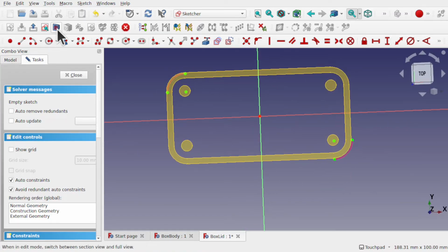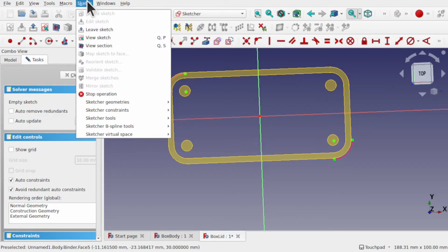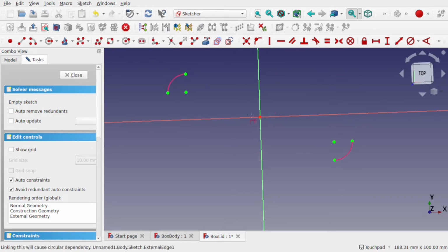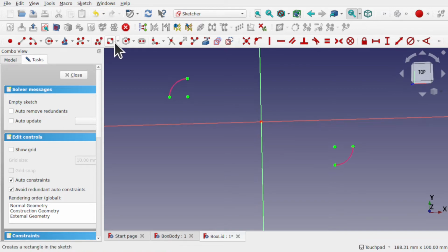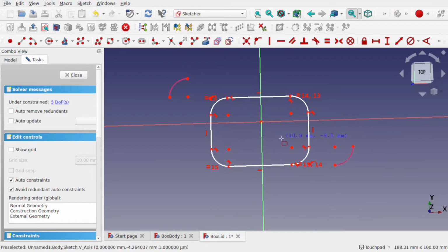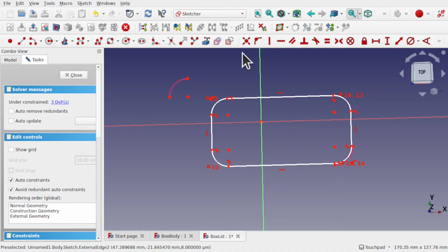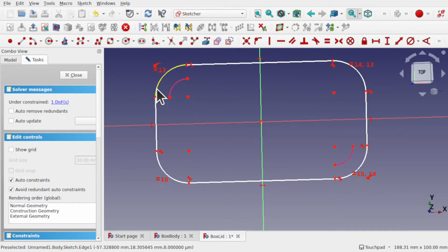At this point we may want to use the section view or sketch view section. So that clears our view away from the shape binder. And we can start using something like a rounded rectangle and place the rounded rectangle in here. Hit escape to get the mouse pointer back, right mouse button, and use these 2 points. See I've pulled in opposite sides. Point on point constraint or coincident constraint, those 2 points. Coincident constraint, and finally we're going to take